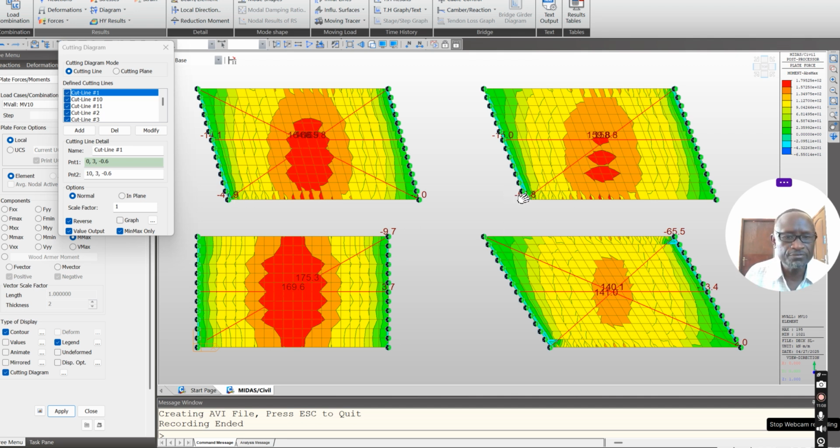Then when you move to the 20 degrees, it is now 15 for the normal straight, and then at the obtuse angle it has gone up to 54, while there is this moment redistribution. The bending moment of 175 starts reducing to 160, and then you get 42 kilonewton meters at the ends or at the edges and corners and obtuse angle. Then as you move your angle to 20, it has also moved from 42 to 54 by about 10, and then the bending moment tends to reduce to about 150.